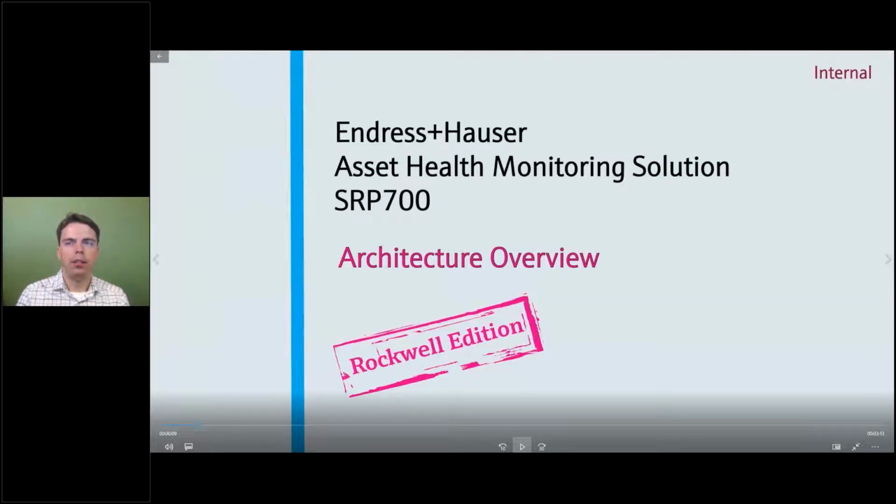So Rockwell made it possible for us to go via the controllers and remote IOs, so from our system straight to the field. You don't need any additional hardware to bypass any controller. We can also do this with Profinet or with Profibus. We also have modules for legacy installations to put it in HART. We just visualize it here, as an example, with Rockwell, but we are open for other topologies as well.